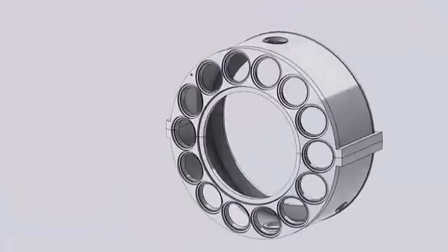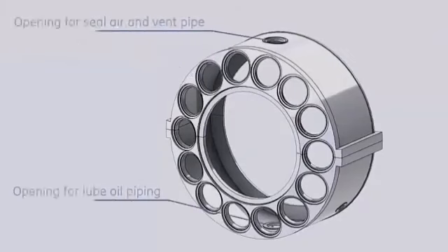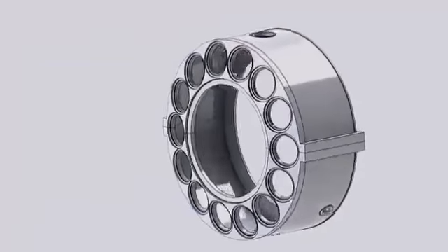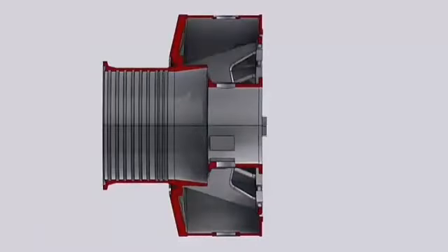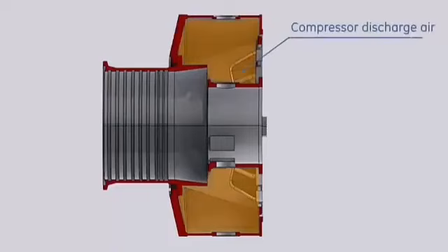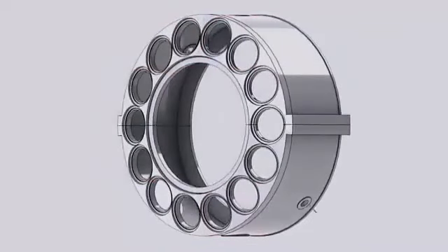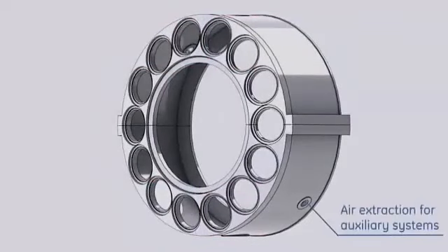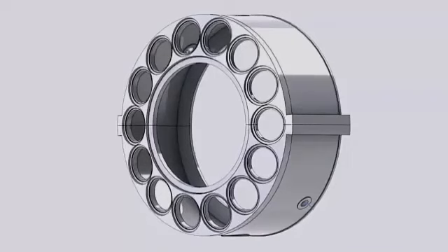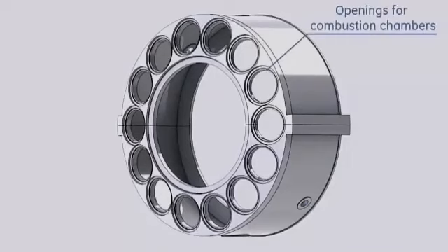The combustion wrapper is a fabricated, horizontally split casing that encloses the combustion system. It provides a supporting surface for combustion chamber assemblies. The wrapper forms a large plenum, which receives the compressor discharge air. This air is directed upstream to the combustion chambers. The forward face of the wrapper is slanted at 13 degrees from the vertical and contains machined openings to mount the 14 combustion chamber covers.